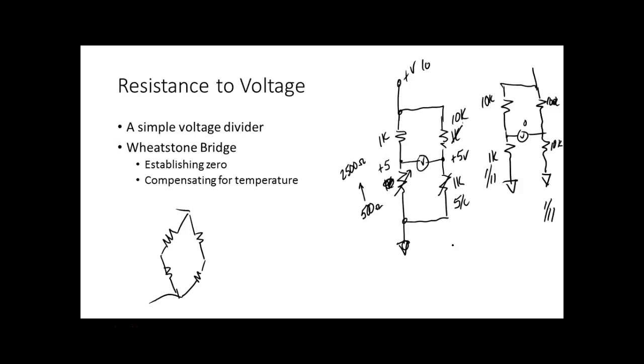If the bridge is balanced, I get 0 volts across the center there, which is going to be the output of the bridge. So the output of the bridge is going to be the center. That's where I'm going to send to my A to D converter, the output of the bridge. But what I can do now is I can come over here and do what? This over here might be a 10K. This right here might be a 10K. I have no idea what that is, right?